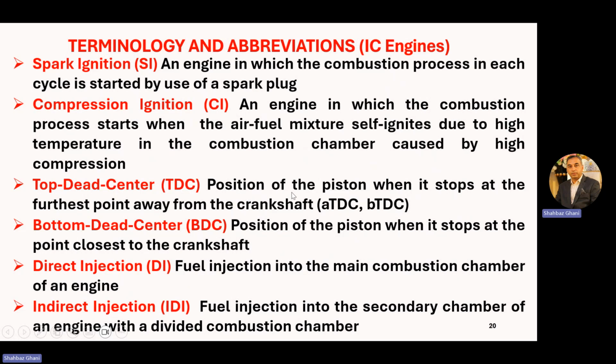Now, the position of the piston when it stops at the furthest point away from the crankshaft is the top dead center. Now, remember these two terms, ATDC and BTDC, very important. The small letter A, when it is written with TDC as ATDC, has a specific meaning. BTDC also has a specific meaning. The position is top dead center. A means after top dead center. B means before top dead center.